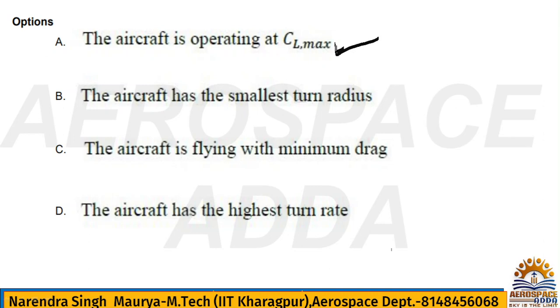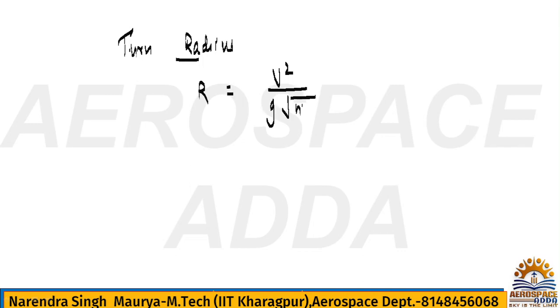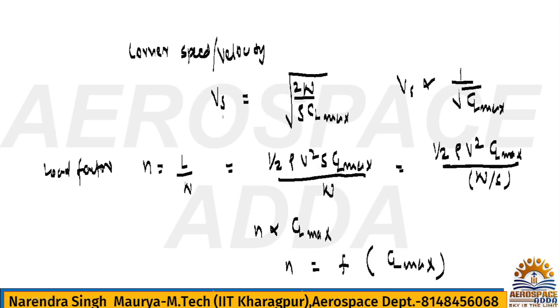Coming to the turning condition, turning flight. What is the turn radius in turning flight? Turn radius, that is R, if you recall, is V square divided by G into square root of N square minus 1, right?